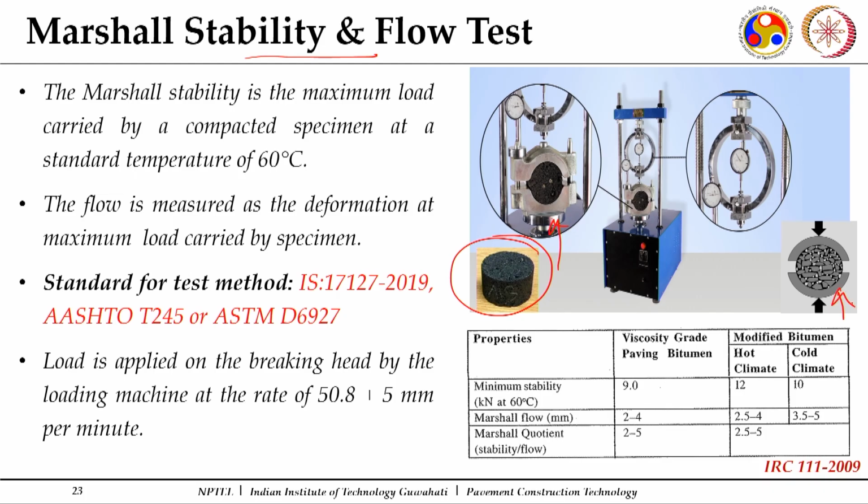This is a confined compressive loading which is given here, and we measure it. The sample is inserted and a load is applied at a standard rate, and we are going to see how much deformation happens in this specimen and how much load it takes before the sample actually fails. So two things are measured: the maximum peak load and the deformation which happens at the maximum load.